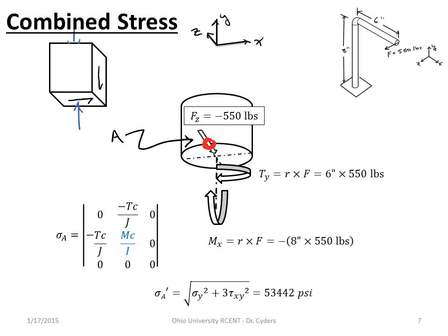So just to go over it one more time, we have shear stresses, tau xy. Remember that in this stress tensor we have sigma xx, sigma yy, sigma zz, tau xy, tau xz, and tau yz, and these follow the orientation with which I'm looking at that element. And so necessarily, if I rotate my frame of reference, I'm going to get a different stress tensor, but the state of stress, things that are summed up with criterion such as the von Mises criterion, that state of stress would be no different.